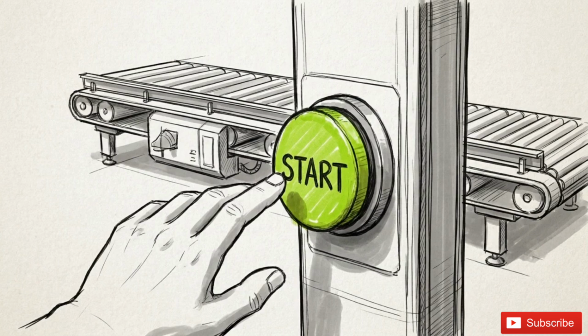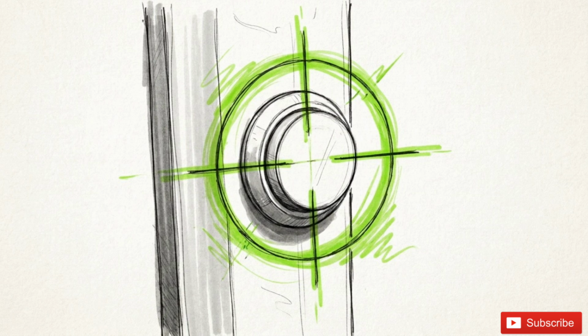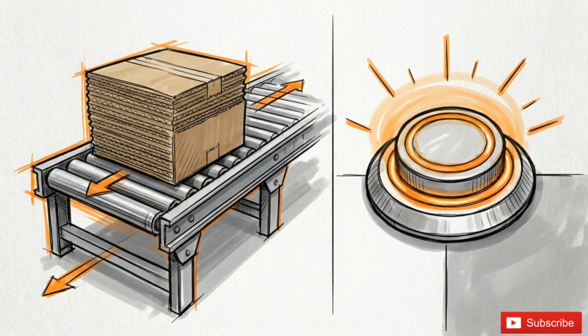It is time for the final test. Click Run inside Control I/O, minimize the window, and hit the play button in your main Factory I/O workspace. Walk up to your operator station and press Start. The conveyor moves, and the indicator light on your button toggles from white to yellow while running.